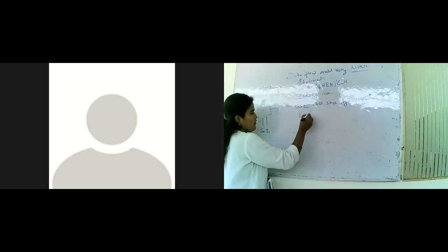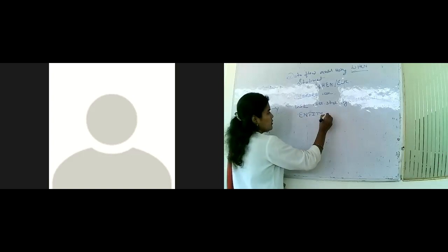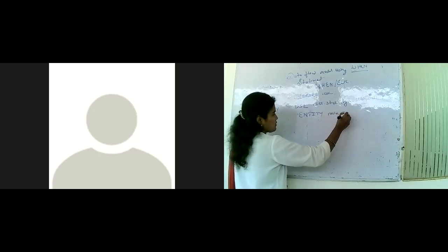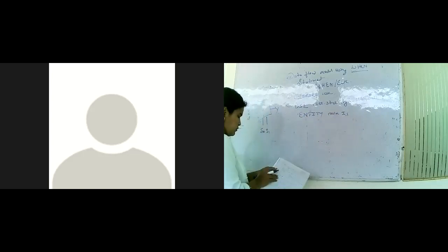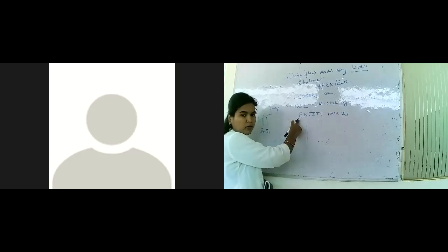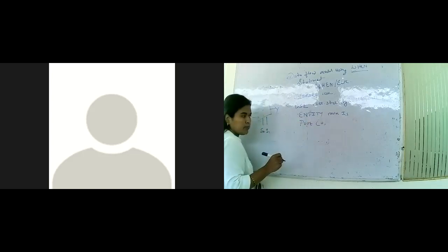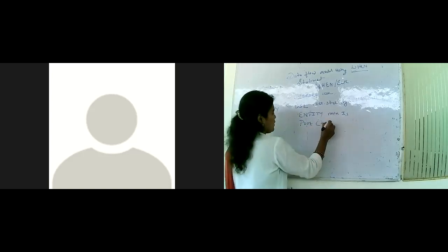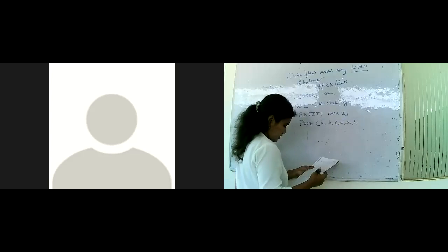Next, the entity section. In the entity section, what will we write? We will write inputs and outputs. Entity, so the name is Mux. The name of the entity here is Mux is. What we will do in the entity is write the inputs and the outputs. What are the inputs here? A, B, C, D, S0 and S1 are the inputs.